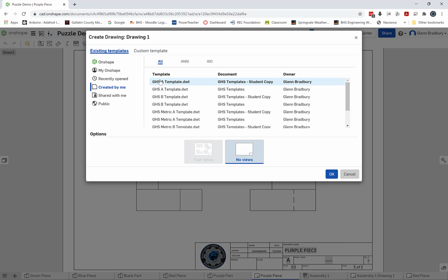We only worry about that on these 3 2-dimensional views. For the 4th view, the isometric view, we're going to right click on that, and we're going to tell it that we want to show the shaded view. And that gives us a color version of that view.